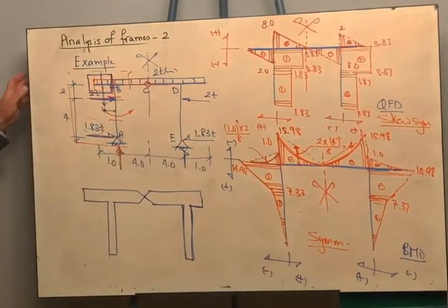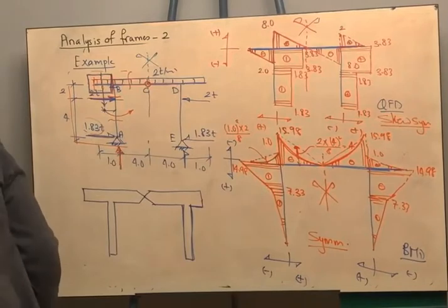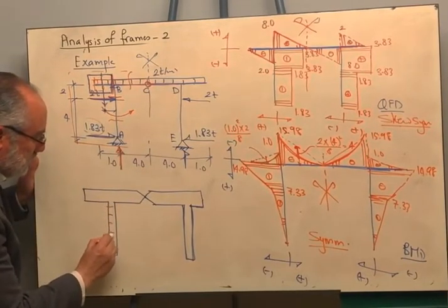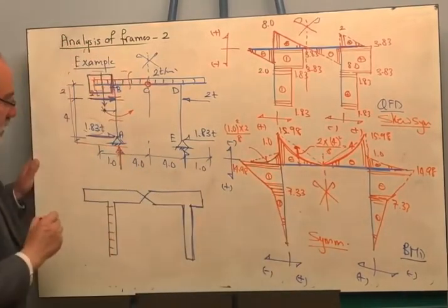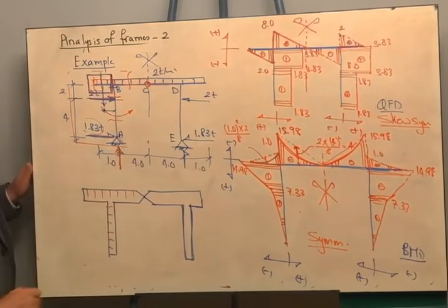Okay? Now the bending moment is drawn on the left. So this means the tension side is on the left. So I am having cracks like this. The bending moment all throughout is above the datum. So therefore this means that the tension cracks will be above the datum.